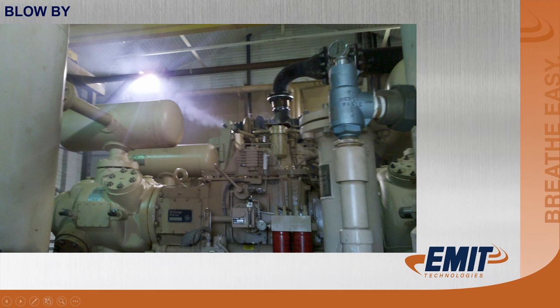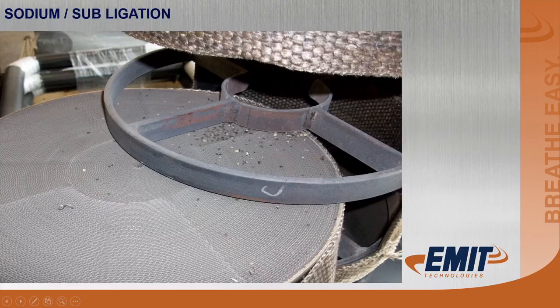So this is a cross-flow aftercooler on this one. The exhaust gases were coming in on this air cleaner and then coming around and feeding the right bank, even though they're going into the left air cleaner. This engine was found to have two bad cylinders in it. They're still running, they were just passing oil very badly.